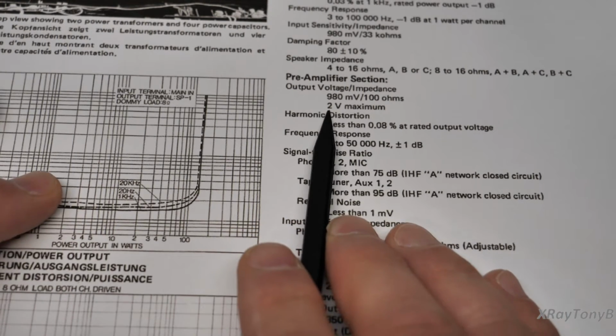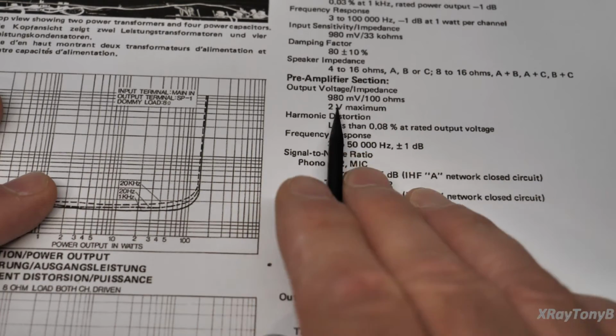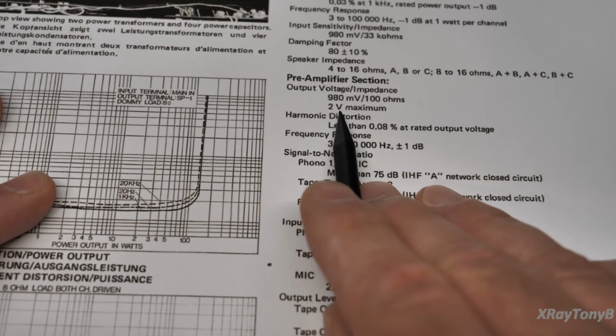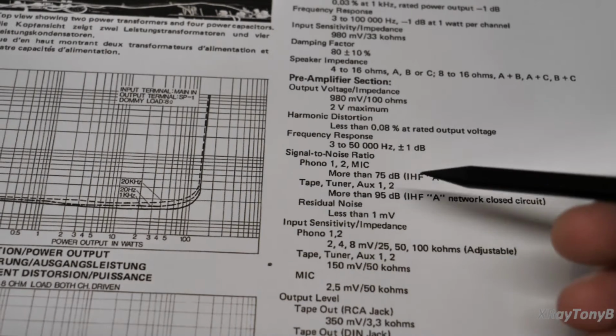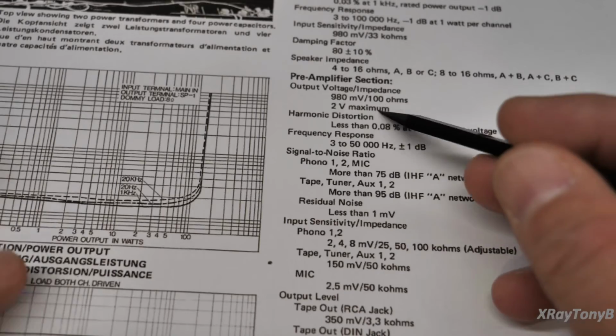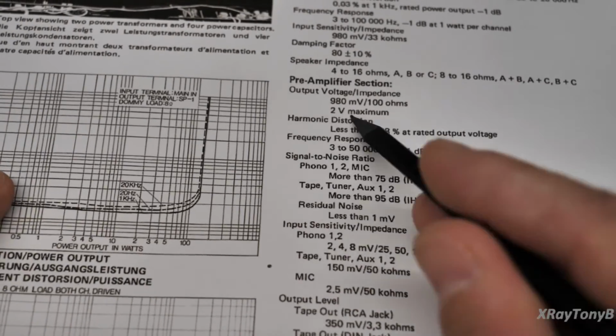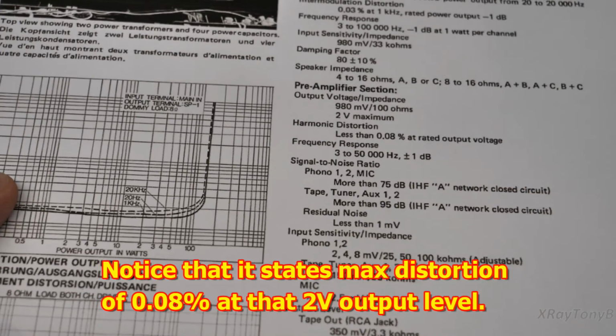So I'm going to do a worst case scenario, and we're going to have an output of 2 volts RMS. You set the input so that the output gives us that through the preamp section. And we're going to look once again at our distortion and see what the distortion in the preamp section is.